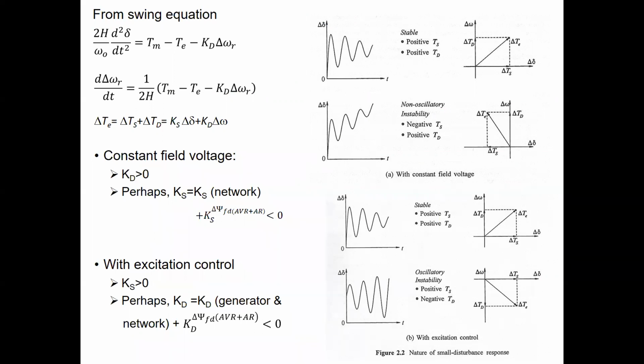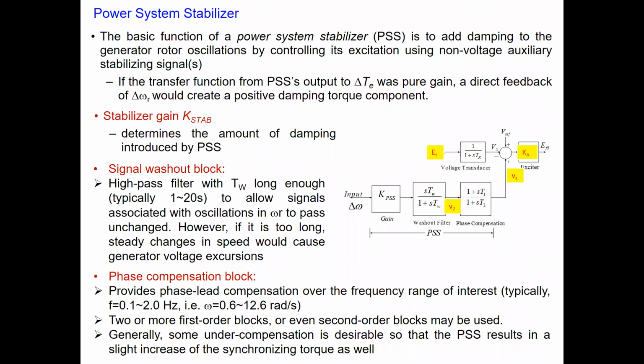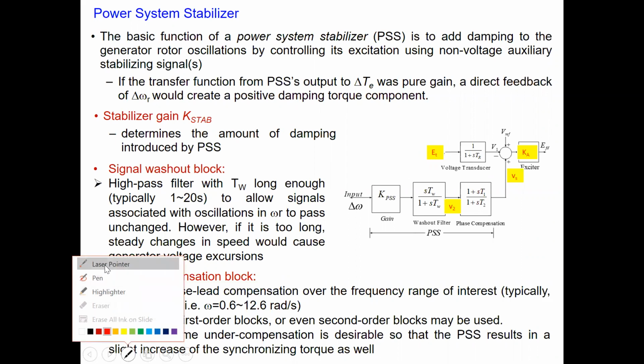But it is important to have the system stable for all the operating conditions. And for that, we design the stabilizer, and we have a controller basically, and we have named it based on its objective. So this controller is meant to stabilize the rotor angle oscillation. So it provides a damping effect. So it improves the damping effect. That means it enhances the damping of the rotor angle response. And thus it tries to damp out the rotor angle oscillations if there are some. So thus, as I said, it is the controller.